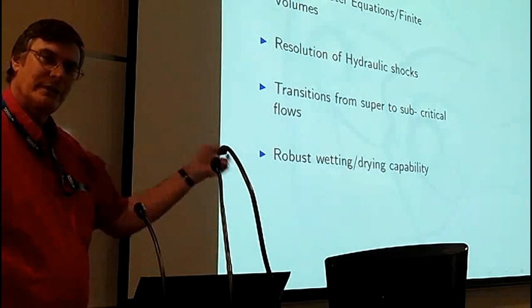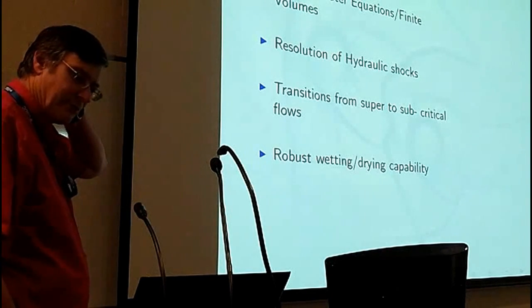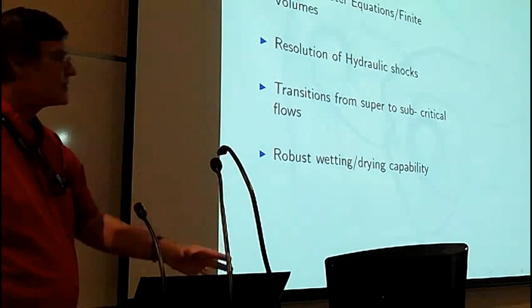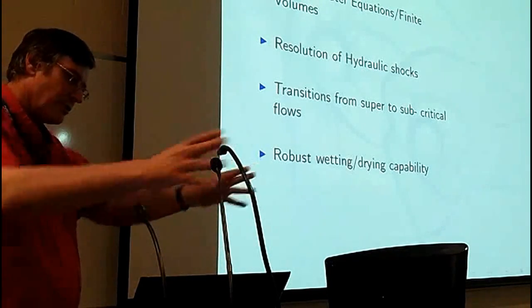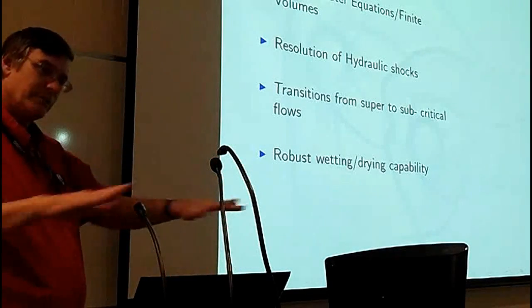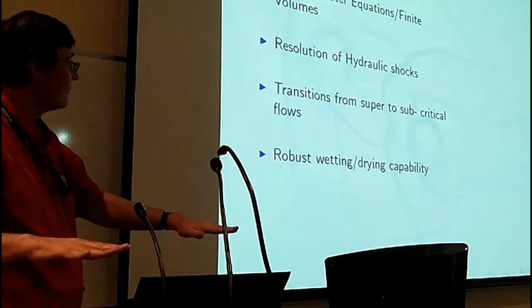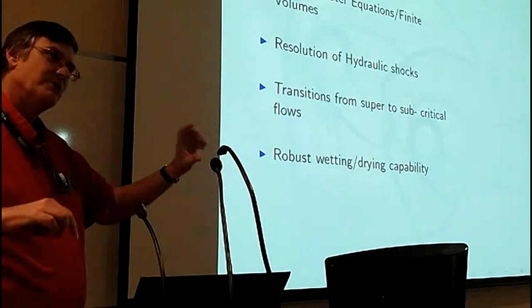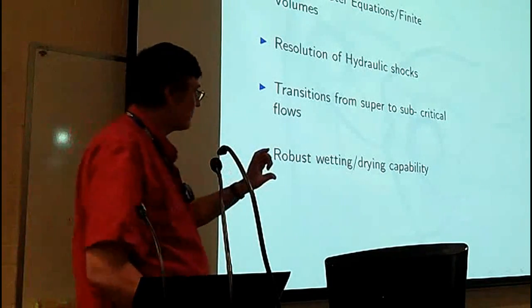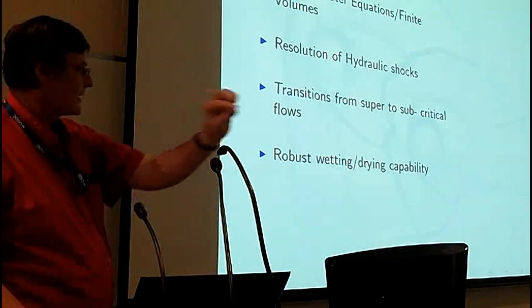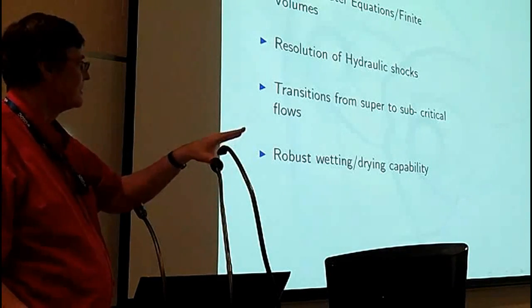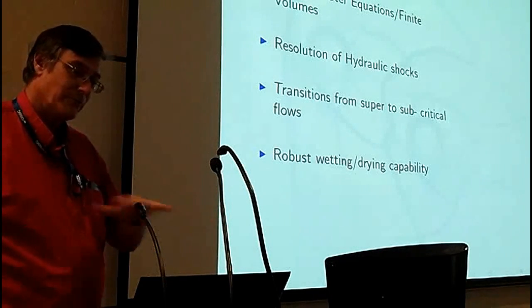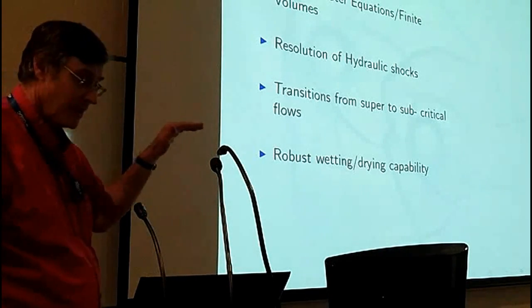So in the piece with New Inventors, we had the water in a basin, and you're getting these hydraulic jumps. So you get the water coming down, going out at supercritical speed, and then the basin sort of stops it, so that slows it down, and that's a much higher depth of water. And then you get this very distinct region that goes from the deeper water down to the shallow water, or from the supercritical flow to the subcritical.